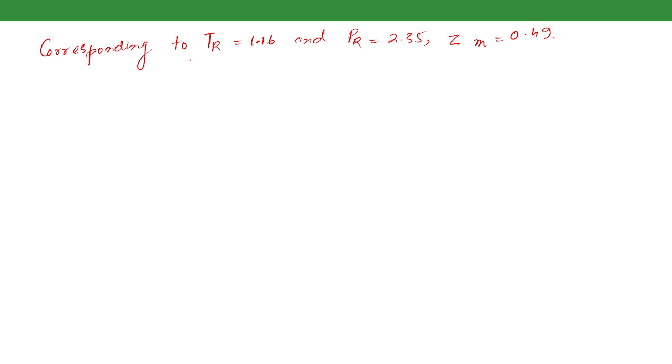So therefore the volume in this case will be equal to the compressibility multiplied by the volume obtained from the ideal one. So this is 0.49 multiplied by 1.330. So this is 0.652 meter cube. Okay. So this is the volume of the mixture as obtained from Kay's rule. I hope it is clear to everybody. If there is any doubt, you can ask.